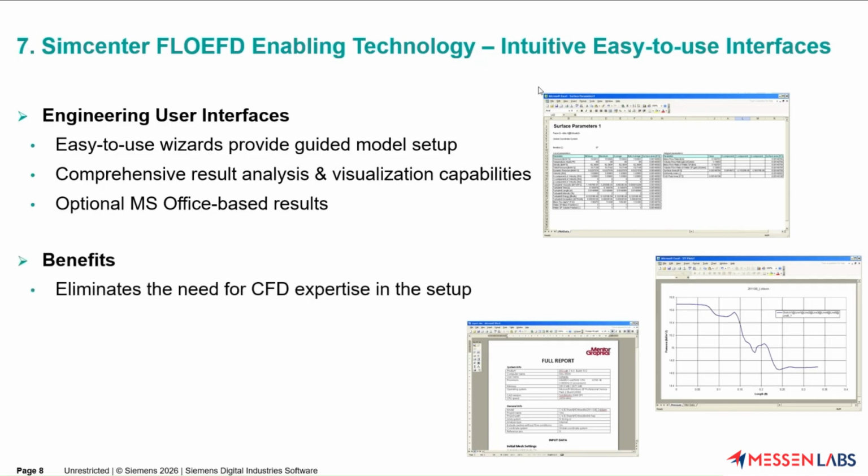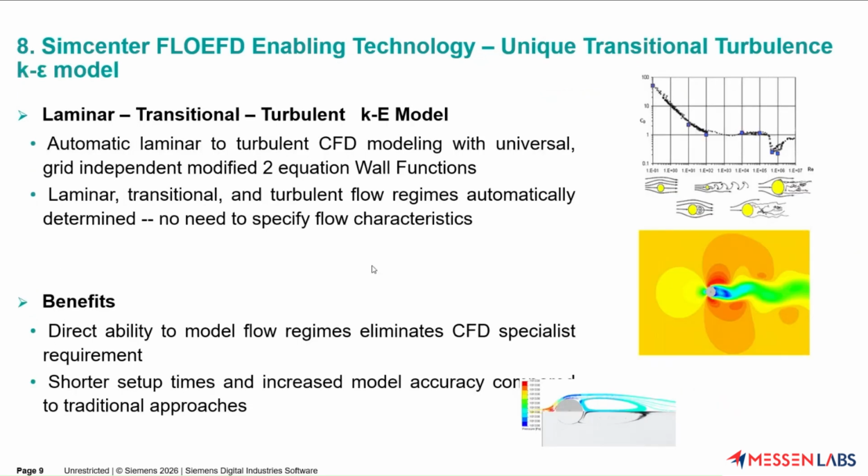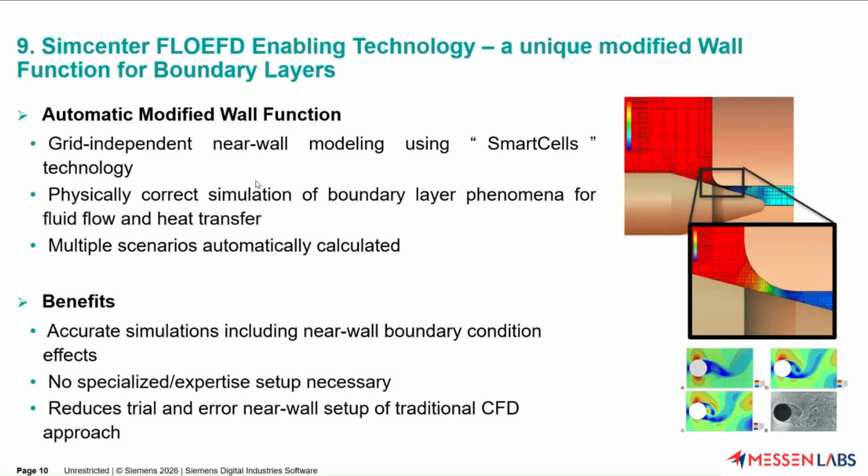So another great feature is the easy to use interface here. You have the wizards wherein you can quickly set up your entire simulation in just a few clicks, and then you can run the simulation and export your reports in detail, and you can automate as well. So as discussed, the turbulence model in the background is the k-epsilon model, which is capable of solving most of the CFD applications.